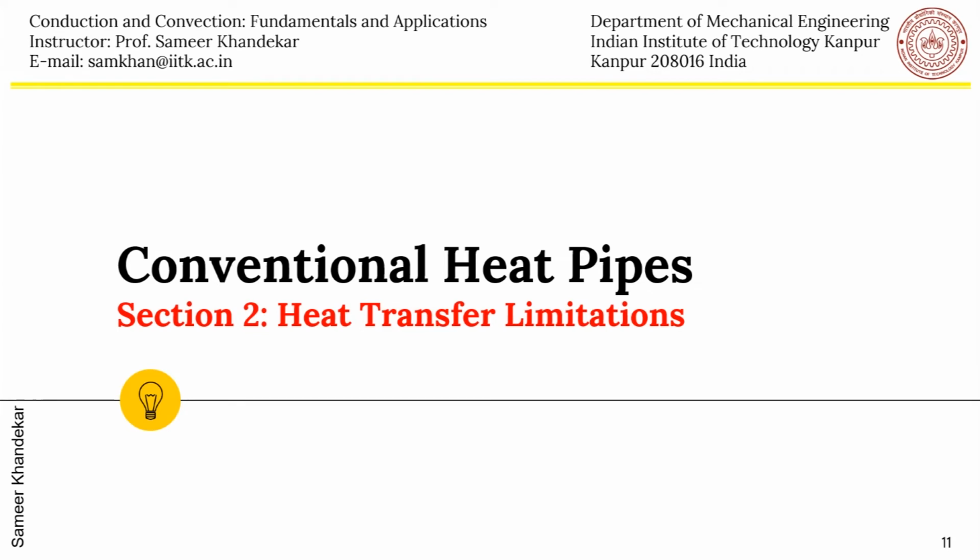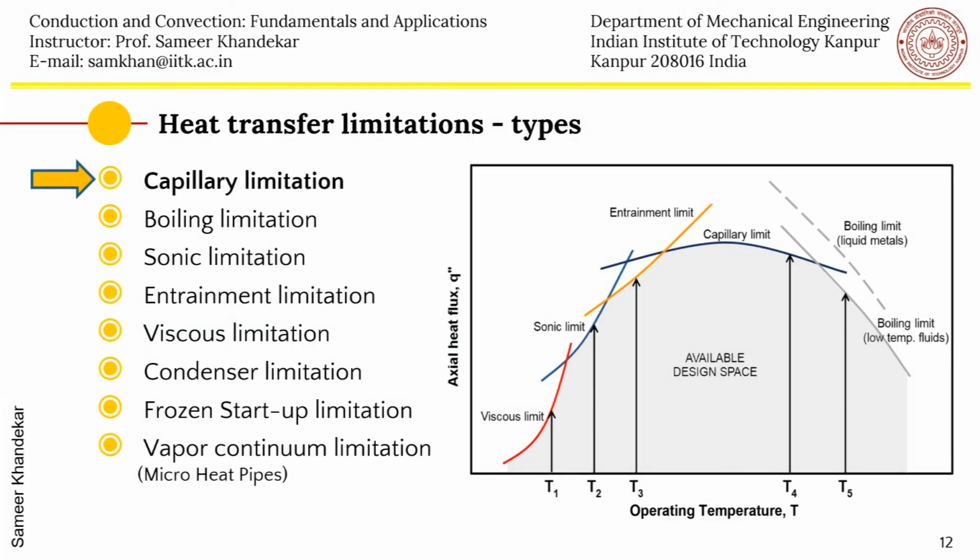As we have been discussing, the operating temperature of the heat pipe for any given fluid ranges from close to the freezing point up to the critical point. We have seen the figure of merit, and we have also seen that at different temperatures it depends on at what temperature you want to take the heat out. Suppose you use water and you want to maintain the temperature of the electronic component at 50 degrees. Then your cooling atmosphere will be of the order of 50 degrees, so that automatically the evaporator temperature will not be very different from that. It will be slightly higher, depending on the thermal resistance. If you want to take the heat at 100 degrees centigrade, then naturally the outside ambient with the circulating water or whatever ambient you are giving to the condenser should be of that order of temperature, so that the evaporator temperature is accordingly adjusted depending on the thermal resistance of the device.